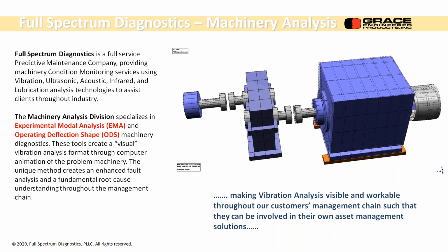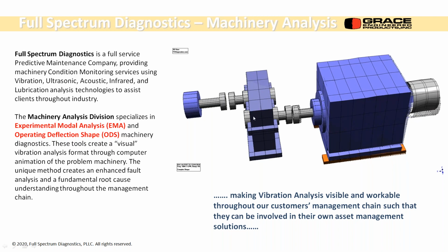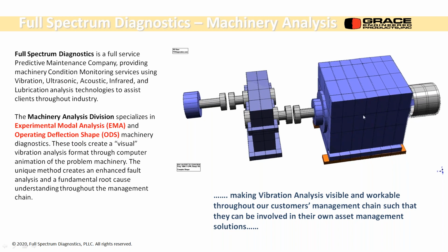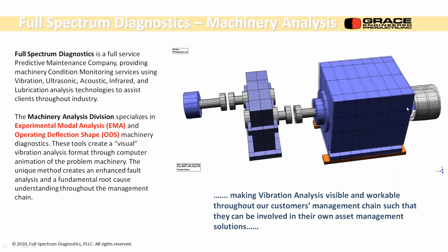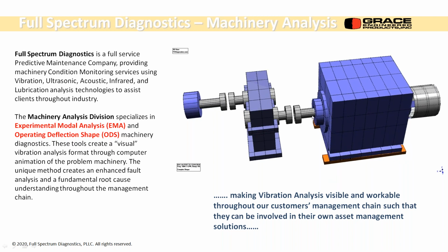The unit you're looking at right now has a steam turbine, a gearbox with couplings on both sides, and it's coupled up to a generator. This was one of the actual problems that we solved. There are probably 300-400 physical measurements we had to put down. But you can see right away, there's thrusting across this coupling.